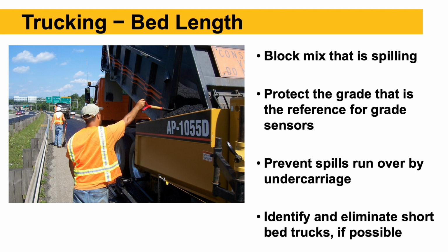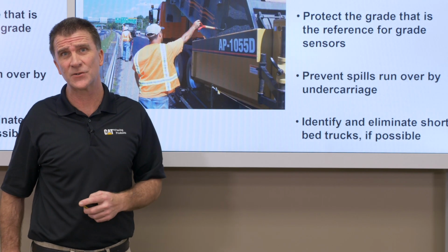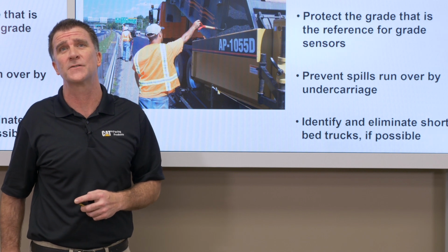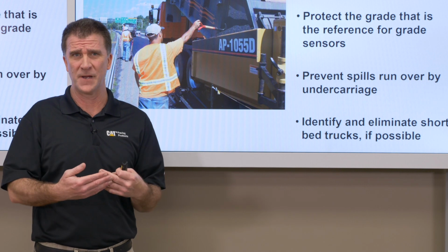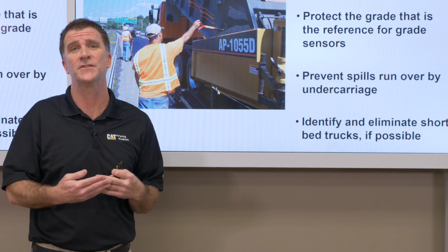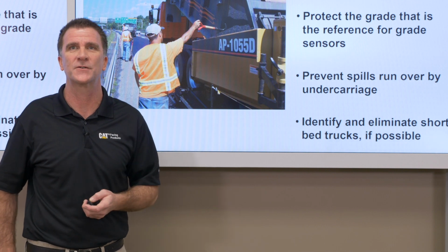And this is something that really goes to the planning part as well, something to look at and hopefully plan ahead of time before the first day of paving. Whoever our trucking company is, or whether it's our own trucks, just make sure that the truck beds are going to fit nicely into the paver hopper. Or on the paver, again, those push rollers are adjustable, so we may adjust those so that the trucks fit better into the hopper.